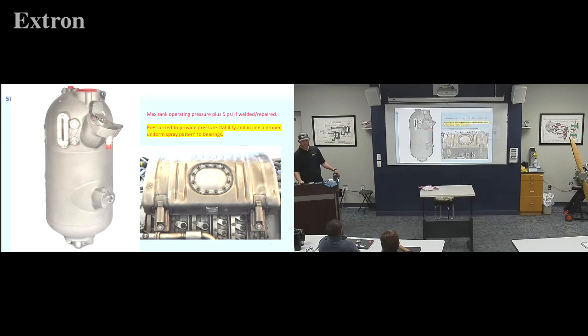That would make sense, because if JZ is saying 2-3 psi, you're going to want to test it at probably twice what it's going to hold, right? Oh, I'm sorry. 5 plus the operating. 5 plus the operating, so I'm way off on that one, sorry. So whatever it operates at, add 5 to that. So, anyway, might not be as much pressure as you think. We don't want our pumps to cavitate, so that's why sometimes they're pressurized.